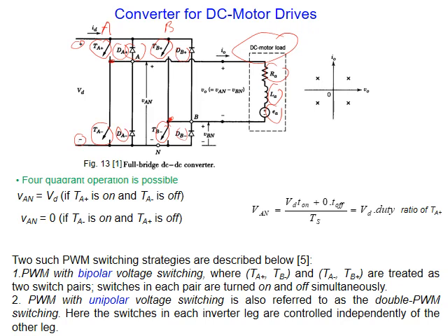You may ask, why do we connect these diodes? First of all, to protect the switch, and to make a path for the current to flow through in situations where the current reverses its direction. For example, when energy stored in the inductance is released, we can use it.